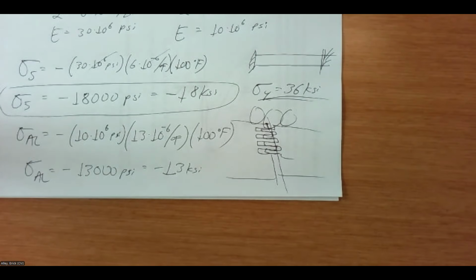Now, if we put these expansion joints in there, we go back to the free end case. We won't build up any of these stresses, and then we're going to be okay as far as the loads. We only have to worry about the weight of the vehicles and the bridge itself and things like that. But if we were to build a single span bridge between, say, two earth abutments, like an arch bridge, and we don't provide any expansion relief, we can build up some really big stresses.